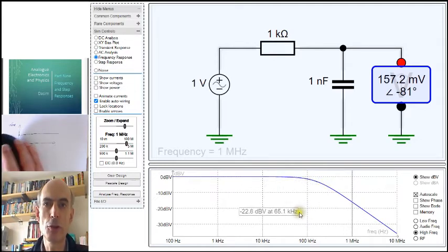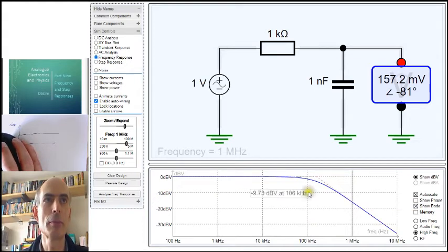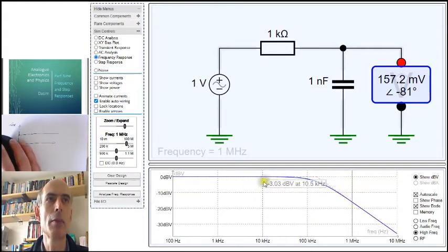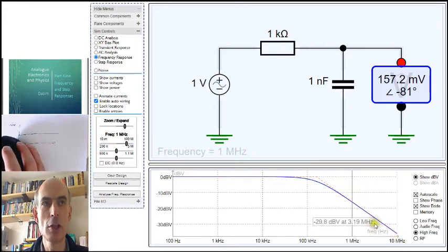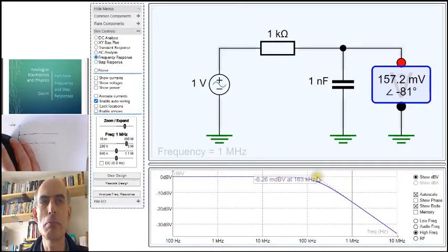If you've come across the Bode approximation, you can also plot the Bode approximation like so. And that would be those 2 low frequency and high frequency lines just extended until they meet at that point there, known as the break or corner frequency.